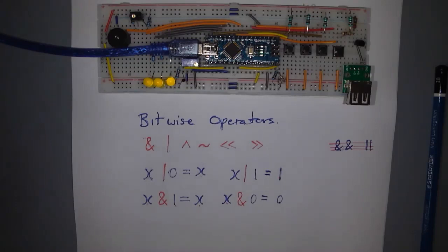Why is that not going there? There we go. It's in there now. So what it's doing is ORing it with the value that's already in there. This will put the new value into only the register bits involved with these 3 LEDs and keep the others the same.